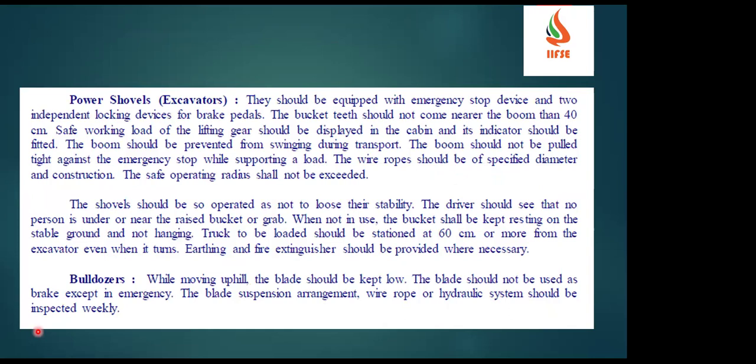If you're transporting an excavator from one place to another, we have to take care of the swinging of the boom. The boom should not be pulled tight against the emergency stop while supporting the load. So it will also have emergency buttons. The extending of the booms should be limited, the wire rope should be of a specified diameter and construction, and the safe operating radius should not be exceeded.